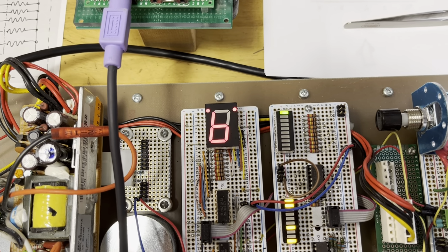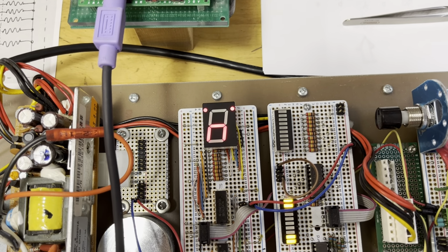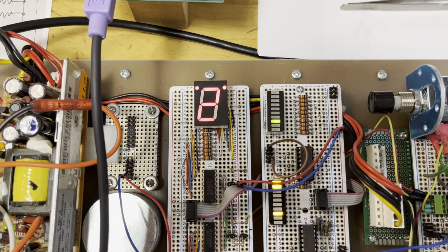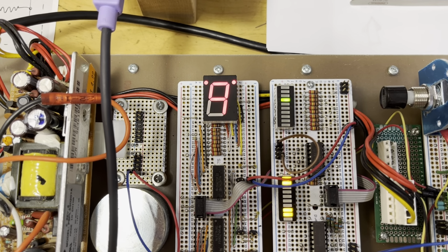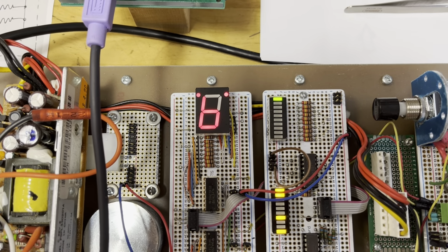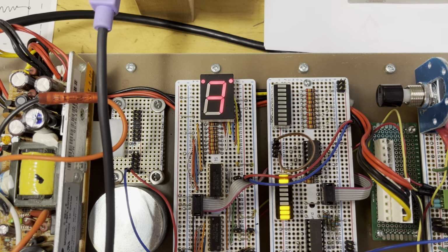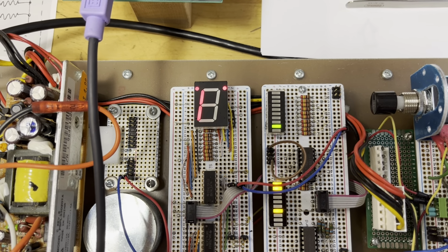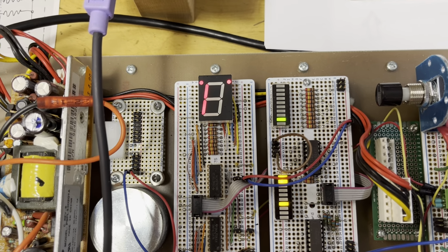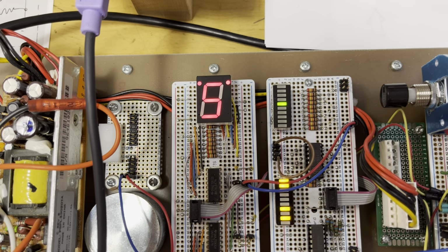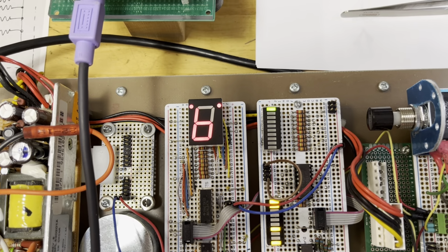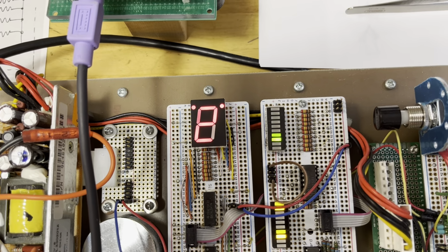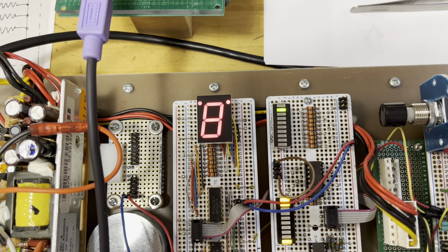If you continue counting, as you can see, the numbers won't be recognized simply because the 7442 decoder is not capable of recognizing numbers bigger than 9. This is why it's called a BCD to decimal decoder. BCD means it's only recognizing 0 to 9, and to decimal is because you have 10 potential outputs here, the green ones, and only one is lit at a time. See, 0, 1, 2, 3, 4, 5, 6, 7, 8, and 9.